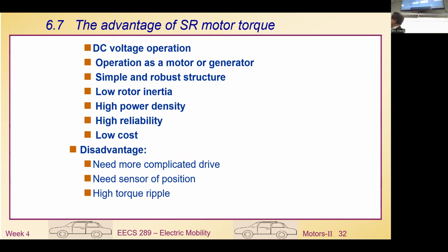And then you also need a sensor, of course. You need to detect which position the rotor is in, and then we energize the corresponding winding. When the rotor pole rotates to here, close to the alignment, we energize the particular winding so that you are able to control. So we do need a sensor. Industrial motors, we don't need any sensor. Sometimes DC motors, we don't need any sensor. We just put the DC or AC into the motor, and it can rotate by itself. But for this one, we do need to understand the exact position, so we energize the particular winding.